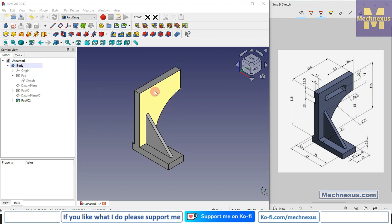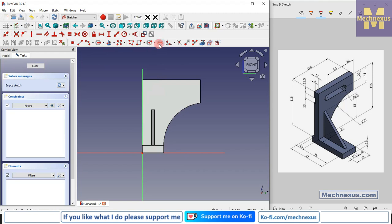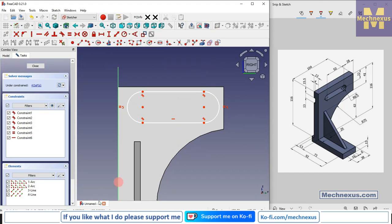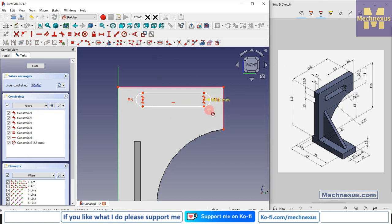Now we will create this slot. So we will select this face and click on the sketch, and here you will get a slot option, and now we will project this horizontal and vertical edge. This is horizontal and vertical, and radius is of 6.5, so select radius and give it 6.5,